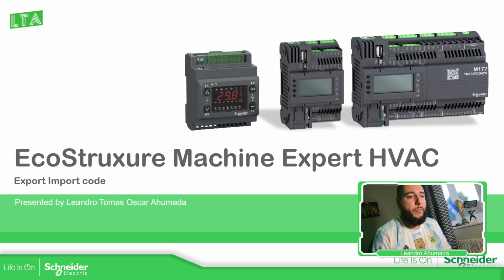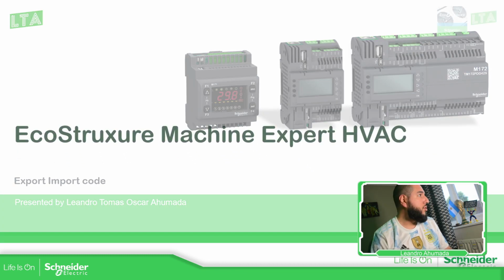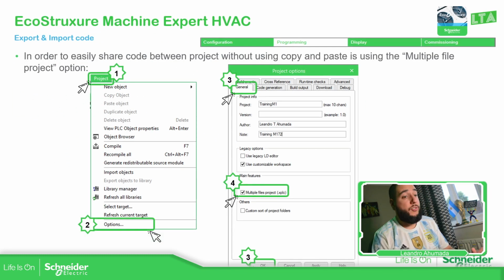So if we want to copy and paste, for example, from project A to project B, some of the variables or some of the GVLs or POUs, you can make a copy and paste if you're using structured text. But if you are using any other language, then you need to copy each rung inside the POU to the other side. So to easily exchange the code and reuse it in a faster way, we have this option in the software.